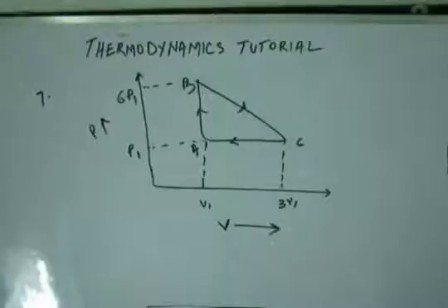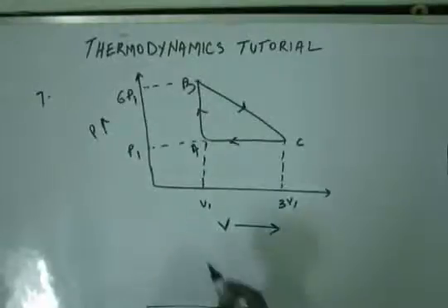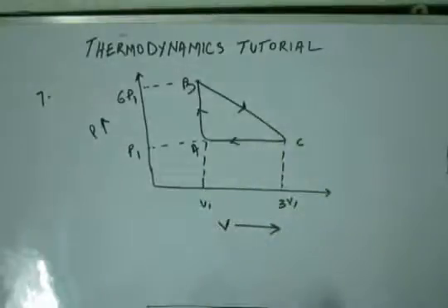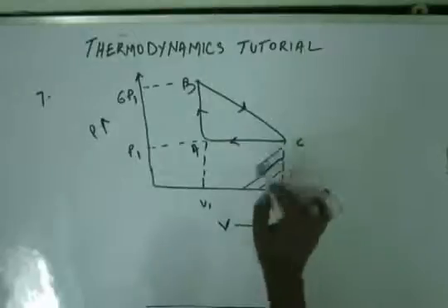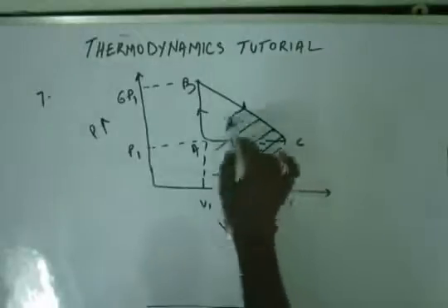Then we have seen this before actually, the area under the curve. And when you have a cyclic process, then the area under that cycle actually provides you the work, the magnitude, and the sign you have to look for. If you're starting from A, then A to B is an isochoric process, work done will be 0. B to C, the area under BC curve. This is BC.